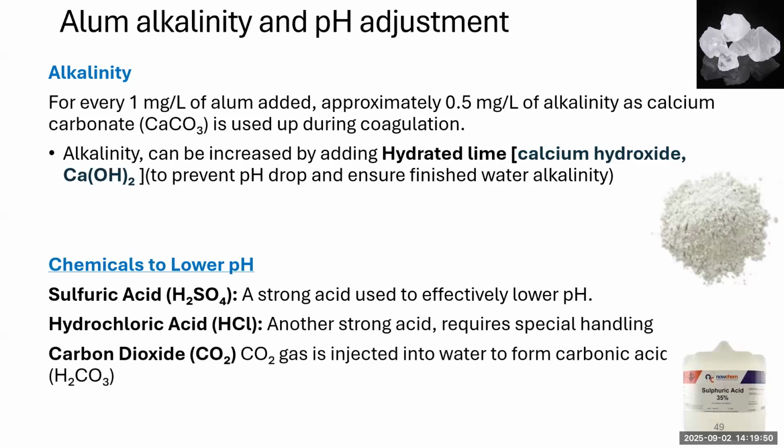And also a very non-hazardous way to do it is to add carbon dioxide, which turns into carbonic acid when it reacts with water. So that's a lot safer way. Not that you want to be exposed to a bunch of carbon dioxide to breathe, but feeding carbon dioxide gas into the water at low amounts to form carbonic acid can help to lower the pH without having to handle acids.